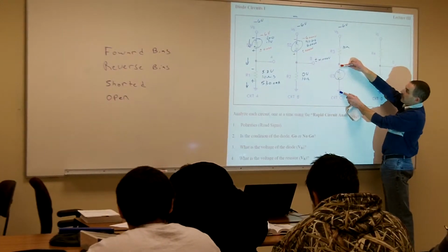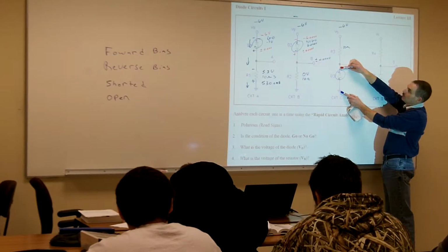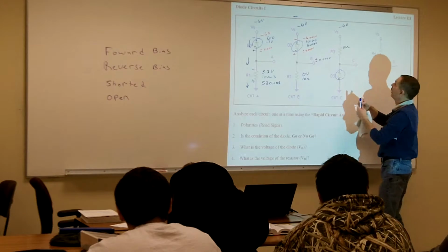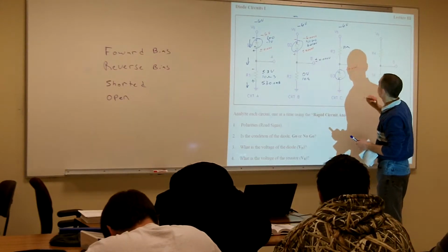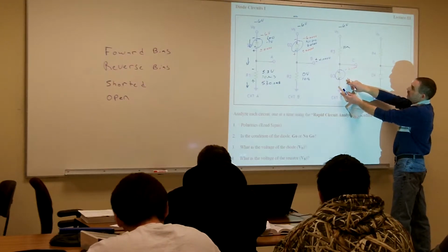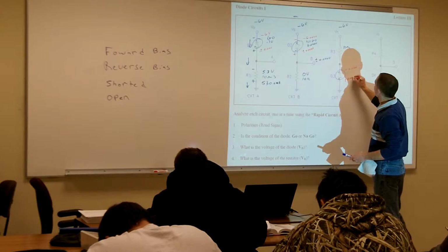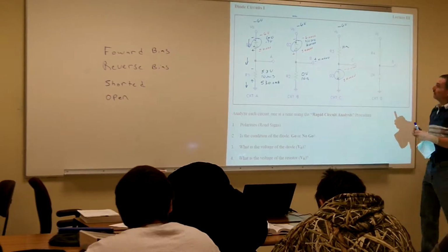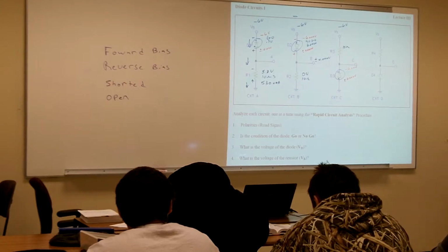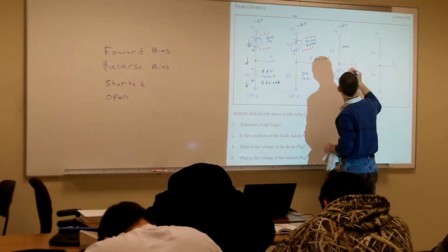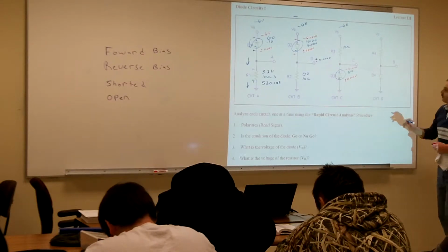So on my cathode, I'm going to measure what for voltage? Negative 6 volts. And then on my anode side, plus or minus 0.0 volts. Okay, is the diode a go or a no go? Go. That's a go. And it's going to drop what for voltage? 0.7 volts.